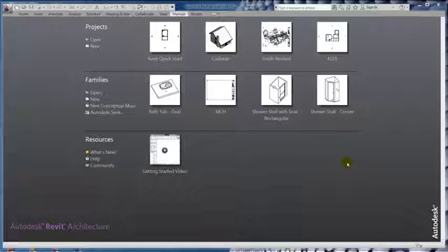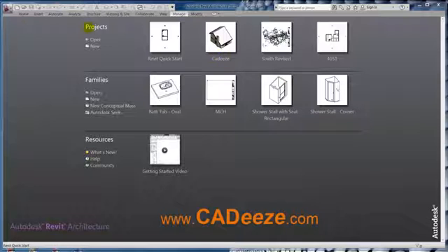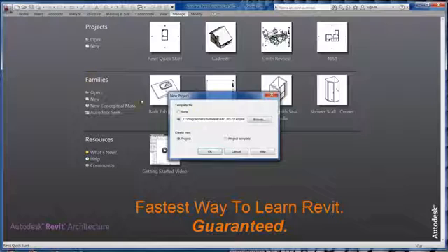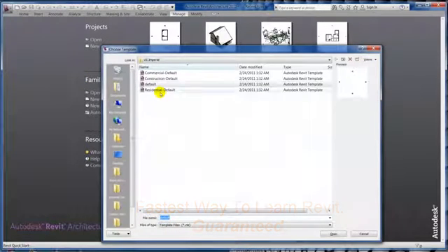Let's go ahead and get started drawing. Let's get you being productive here. Go under the Revit application menu, hover over New, or hit the little black triangle there, and Project. And we're going to come over here and pick the residential default.